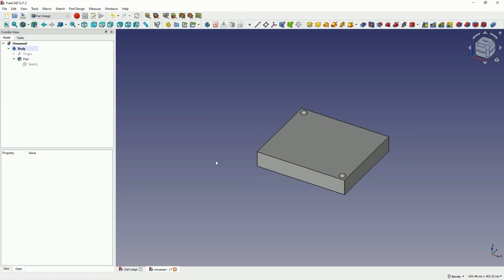In the previous lessons, we created a simple 3D model, and at this stage of learning, it is worth discussing navigation issues. When it comes to navigation in FreeCAD, we have navigation styles available in this location. If you click here with the left mouse button, you will expand the list of navigation styles and you can choose the style that suits you. I have chosen the Blender navigation style. When you select a style, if you hover the cursor over this area, a tooltip will appear.